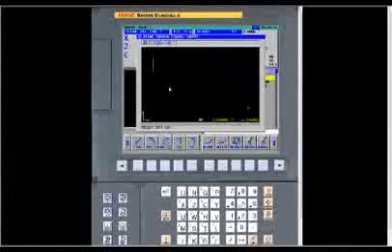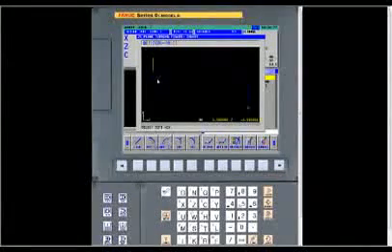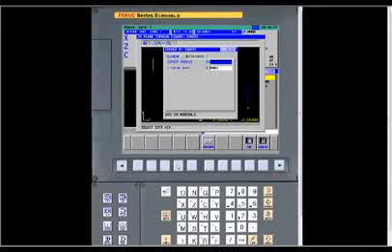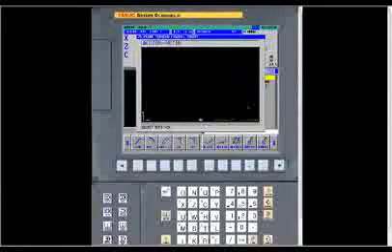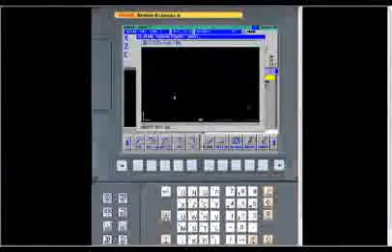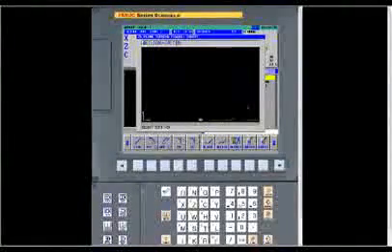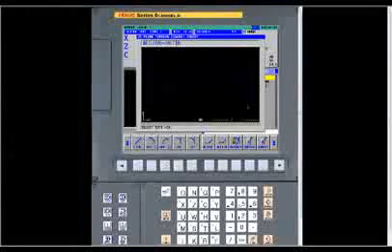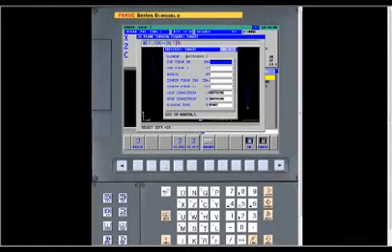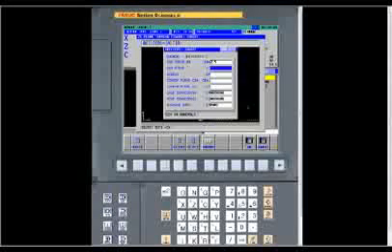It drew the radius, a real small flat, and then another big radius. Now up here on the top, I want another corner radius, 60 thousandths. Say OK. Again, it didn't draw it yet because it doesn't know which way to go. Now at this point, we're going to do another arc. And I know the end point this time, we want to go 2.5.